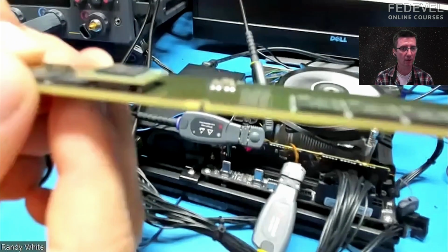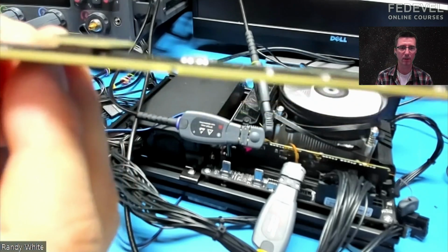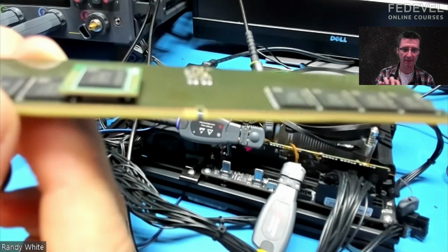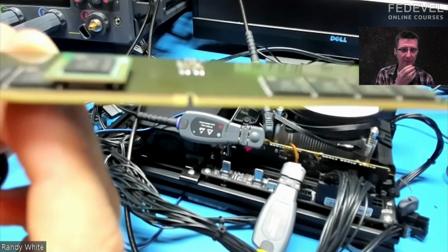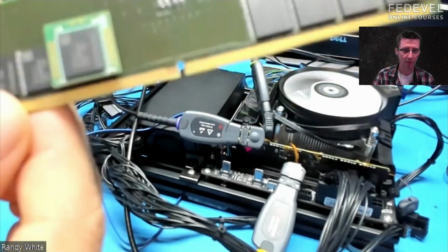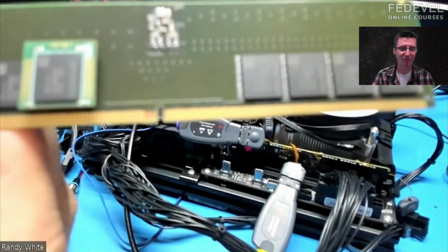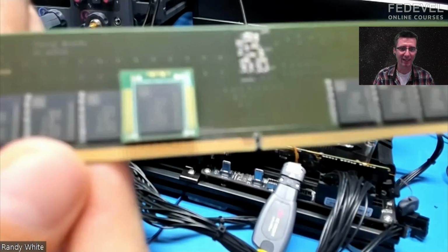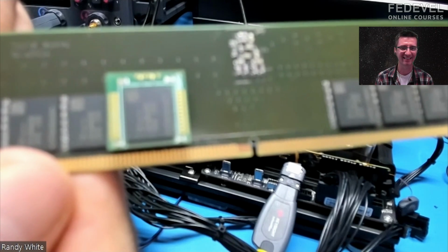Yeah, so tight. I didn't know something like this can be done, because I was a little bit worried that on many boards I design, memory chips are very close to each other. I knew I would need an interposer to access the signals, but I didn't know how I could fit this interposer when there are chips close to each other. Now I can see how it is done.